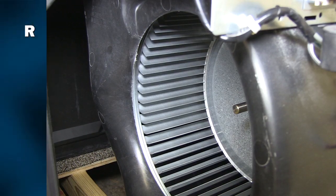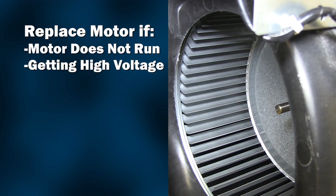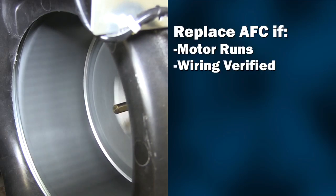If the motor does not run and you have verified high voltage to the motor, then the motor must be replaced. If the motor does run and wiring continuity has been verified back to the airflow control board, then the problem most likely is with the AFC board itself. Replace the board and retest.